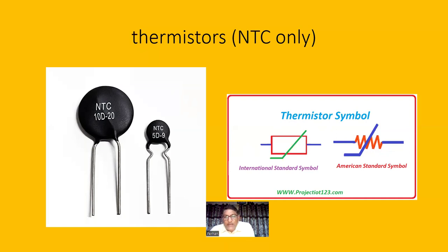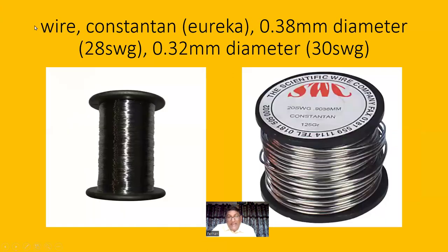So here you have a resistor, and then you have an ice hockey stick on it. So I call this ice hockey. So this is a thermistor. What happens with the thermistor? What happens if the temperature of the surrounding increases? The thermistor's temperature increases, its resistance becomes low. And when the conditions become cold and the temperature drops, its resistance becomes high. So that's the thermistor.